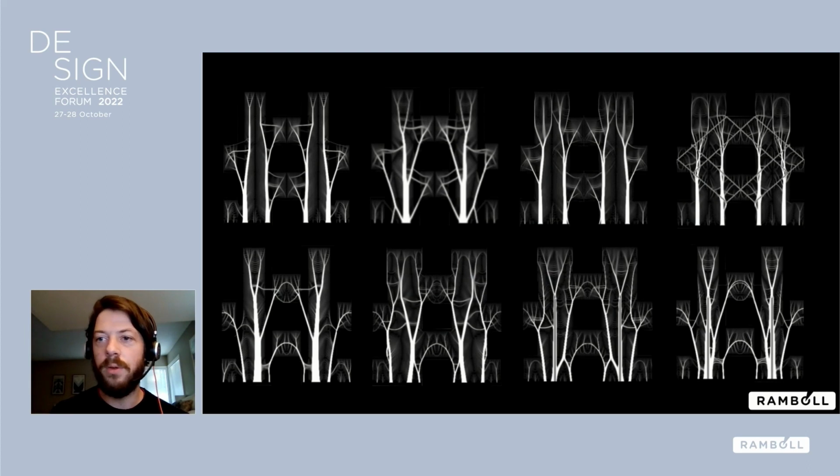Every trick in the book, almost. There's branching strategies, there's tie strategies, there's catenary and arching going on in all of these things. So rarely does nature, when you give it the freedom, decide to go with a straight column or a straight beam. In fact, it avoids right angles and straight lines at every opportunity, electing for more efficient load paths through curvature and branching strategies.